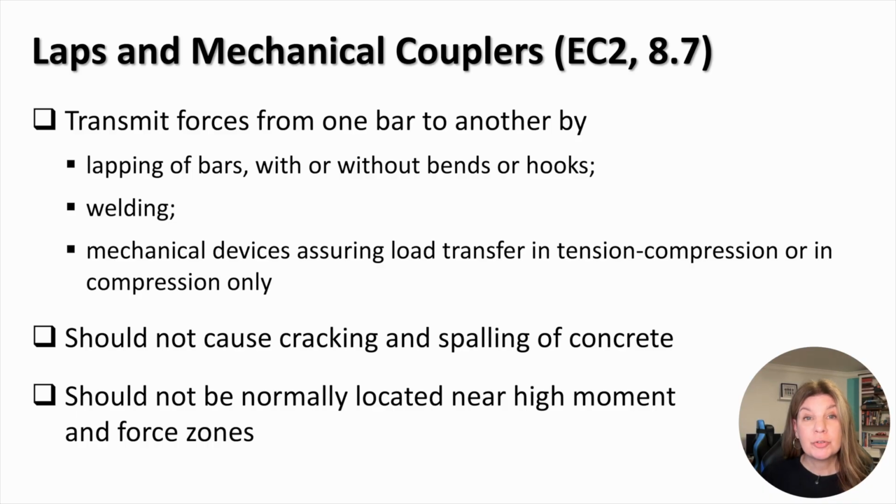The length of reinforcing bars is limited by shipping and handling constraints. Therefore, laps are used to transmit forces from one bar to another within concrete members. Lapping of bars can be done with or without bends and hooks, welding, and using mechanical devices. It is important that laps do not cause cracking and spalling of concrete. Laps are not normally located near high moment or force zones.